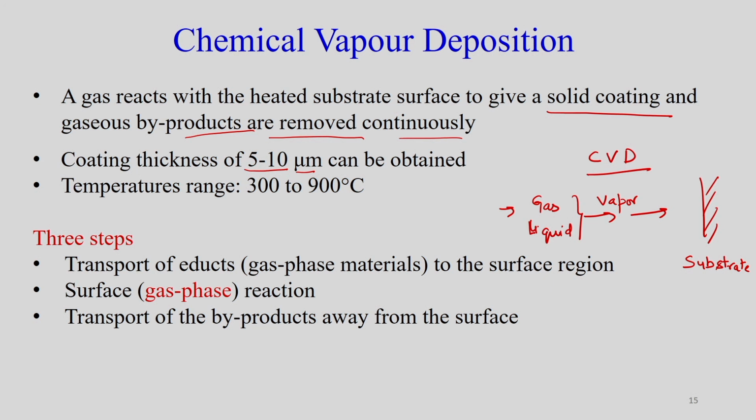So, either you go for PVD or you go for CVD. With time, this will be the coating thickness, it will keep on increasing like this. Again, this depends on what the target material is and what the rate of deposition is. Rather than reaching a plateau, it can also be a straight line, meaning with an increase in deposition time the thickness is increasing.